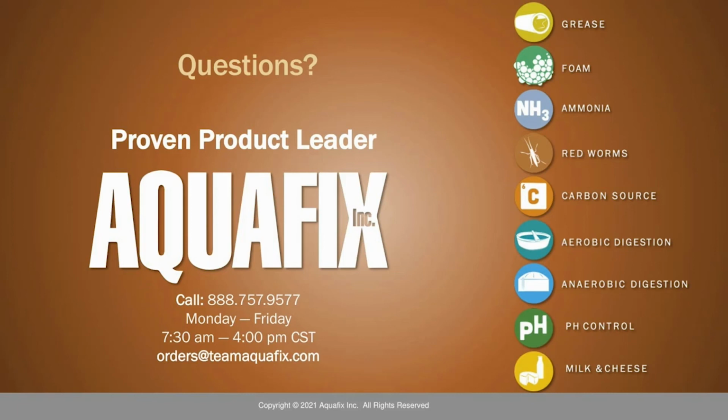From my experience, quats are interesting. They're a very stable molecule. They tend to not have much of an effect on pH in systems. As far as intracellular pH, I am not sure I know the answer to that, but I would like to look into it a bit more because that's an interesting point. But generally speaking, I would see toxicity to both hydrogenotrophic and acetoclastic methanogens if toxicity is in fact taking place.